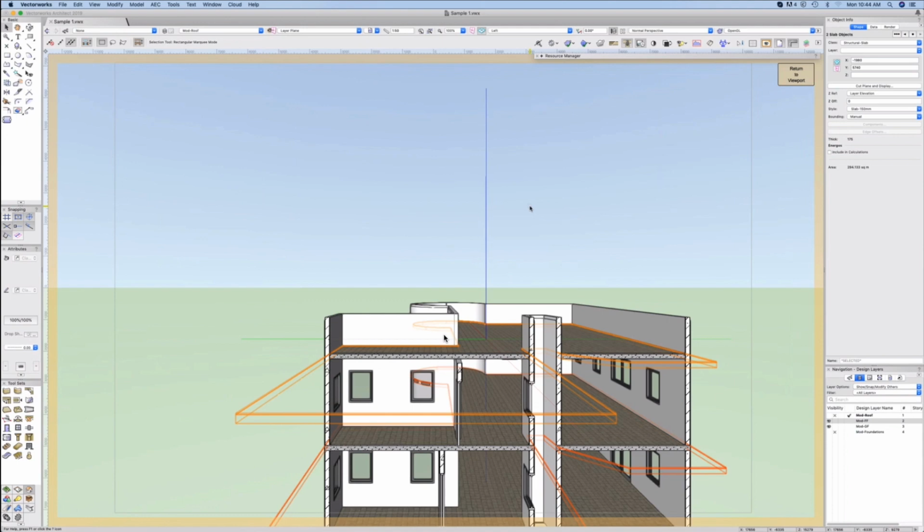Look, you know how you do your construction over there better than I do, but what I've shown you is there's either way to do it. You either build on top of the slab, which is what you said you probably would do. That's what we do. In the UK we tend to build the walls, then put the first floor slab inside of those walls, like a suspended timber floor. But for concrete, we build them floor by floor. You get a nice platform and then you work on top of that. Nice and simple concrete construction.